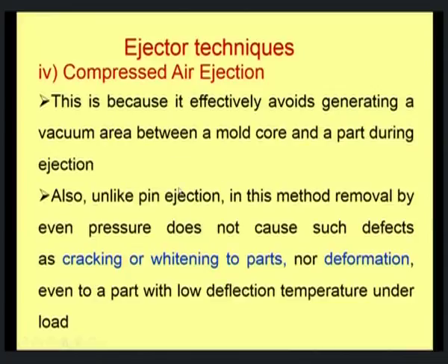And also, unlike pin ejection, in this method removal by even pressure does not cause such defects as cracking or whitening to parts, nor deformation. These are the typical defects that are normally found in pin type ejection, and this method also works even for a part with low deflection temperature and load.